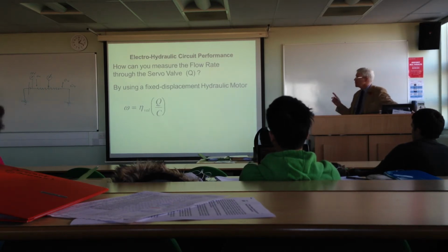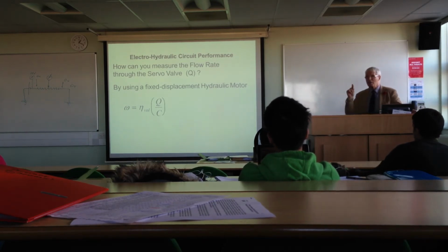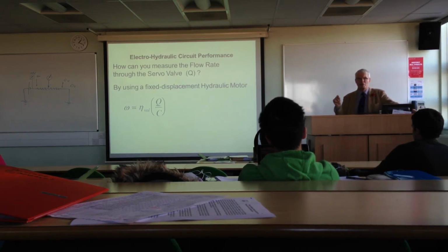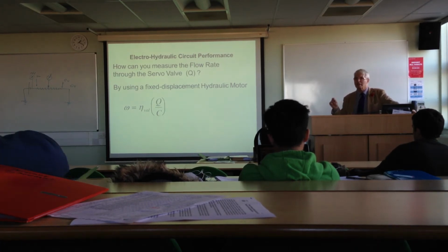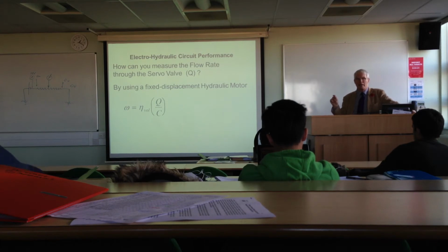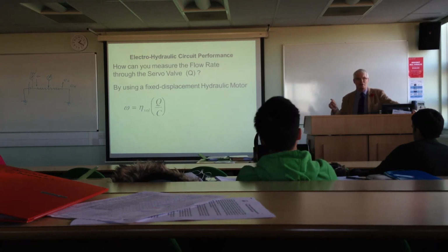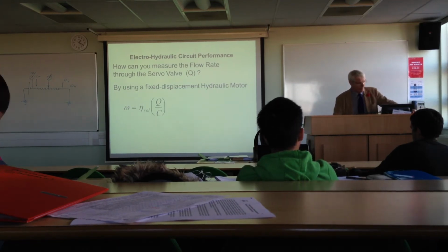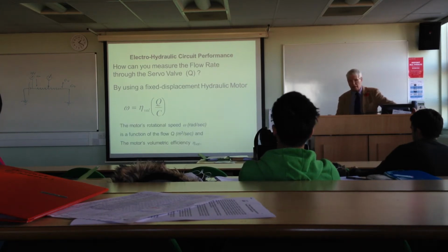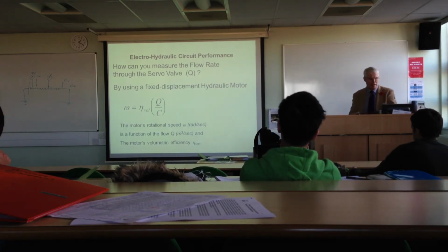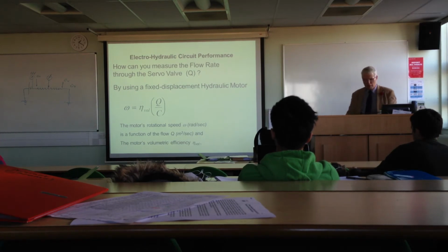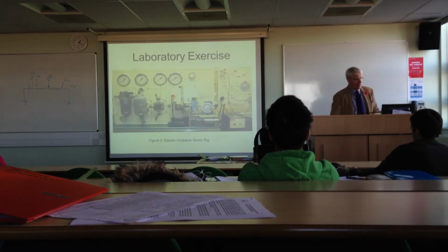The other thing, just to remind you, which I did earlier on, we used that hydraulic motor. Because we can assume that the oil is incompressible, it's not really, but it's not far off, then we can actually predict that for a certain number of revolutions of a motor, we know exactly how much oil has gone through it. Okay. So we've used that. When we go back and look at chapter 3, I want to talk about the efficiency a little bit more. So if in doubt, remind me.